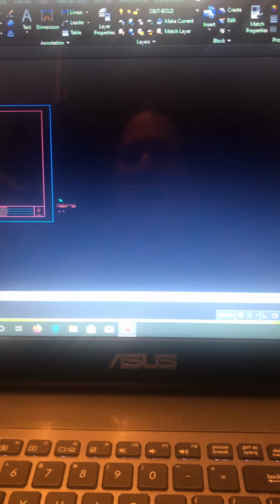So you have a draw section. It has an option to draw lines, polylines, circles, arcs, rectangles, ellipses, and then your hatch. Your modify portion has move, copy, stretch, rotate, mirror, scale, trim, and if you hit this drop down button here, trim and extend, they are sister commands of each other.